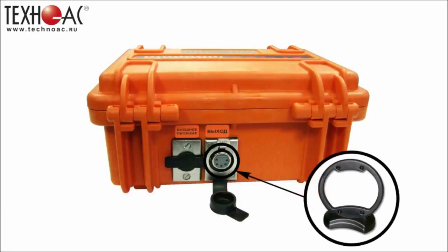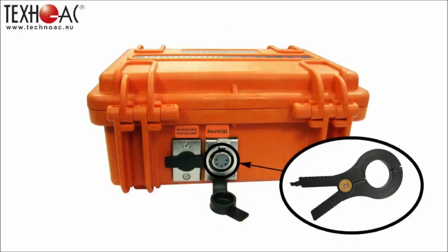Before direct connection to the utility, make sure that the surveyed utility doesn't carry any voltage. The direct connection method is most effective for location but cannot always be used for cables under voltage. In case of location of a live cable, use induction connection with the built-in or external antenna or inductive clamp. Warning: all connections and disconnections should be made with the transmitter turned off.